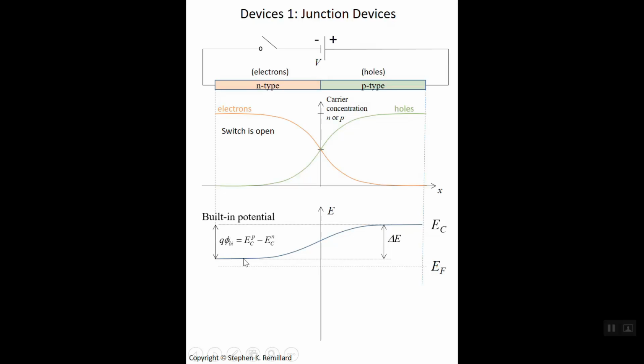So the electrons go into the p-type because there's a low population of electrons over there, and that's what diffusion is, going to where their population is low. But when they get there, they find themselves to be electrostatically unwelcome, and so they roll back downhill. So that's the conduction band edge. All free electrons have an energy that is higher than this energy called E sub c.